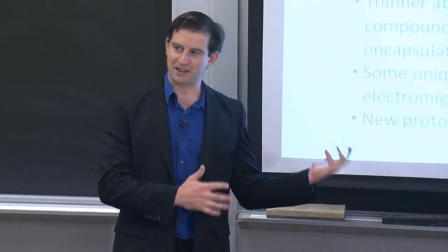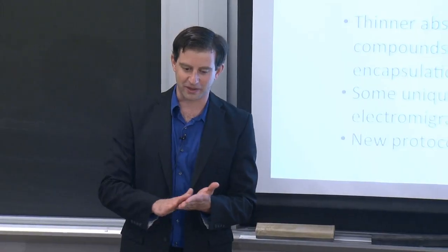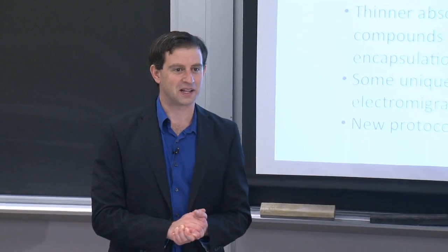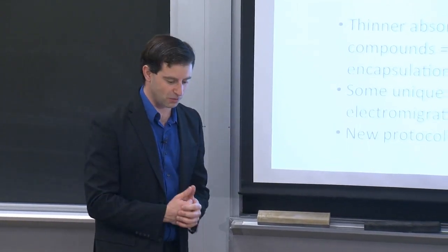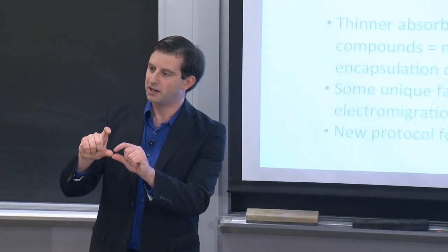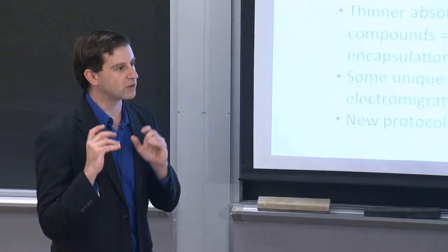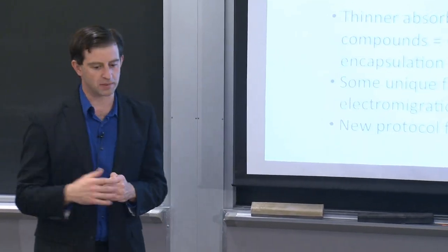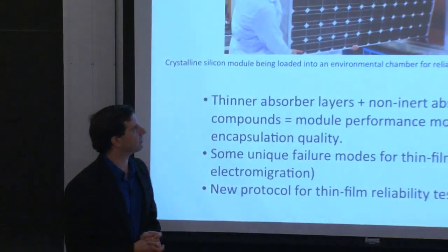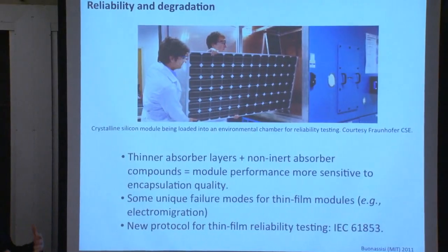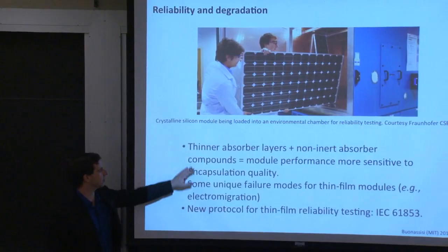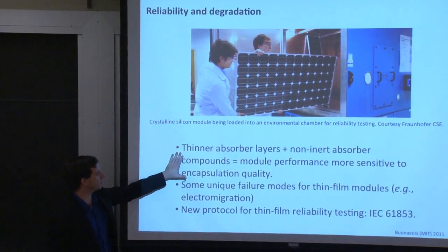But now if you take a fairly reactive thin film material that might react with air or might react with water, and it's so thin that these rusting modes or reaction modes, the weathering modes, can really impact a large fraction of the thickness of your device, you become a lot more sensitive to accelerated degradation. You become a lot more sensitive to the elements, and this includes both oxygen and water. So if the ambient is able to penetrate through the encapsulant and get to the active absorber material, you may have accelerated degradation of module performance as a result.